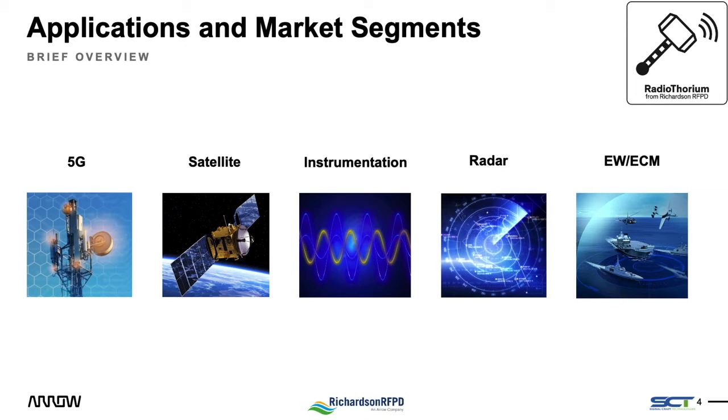Integration with dual polarization, high element count antenna arrays is one of the many use cases that we are promoting. Under commercial communication systems, I should potentially include microwave backhaul point-to-point radio links in the licensed bands from 24 to 42 GHz, which have stringent requirements for linearity, not as much on channel bandwidth support, but in any case, our unit will perform just fine in those conditions.